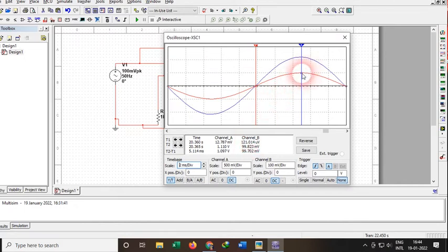And here at the topmost part, it is currently at 99.823 millivolt. This wave's highest portion, the voltage peak, is 99.82 millivolt. So we have given around 100 millivolt, and we are getting around 99.82 millivolt peak to peak voltage from this input source.